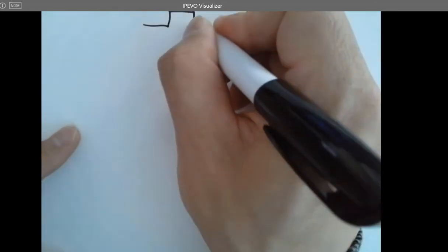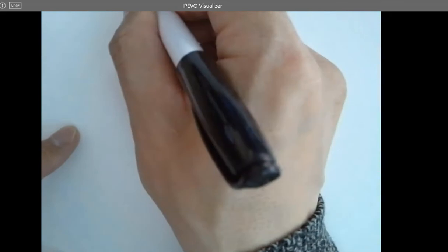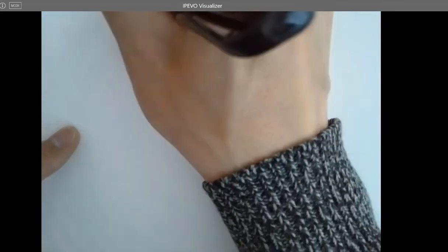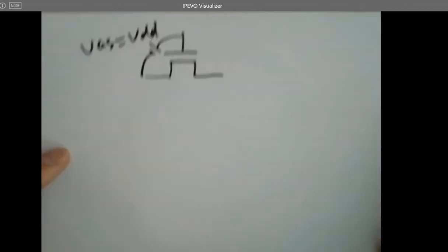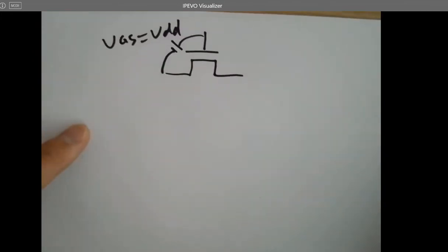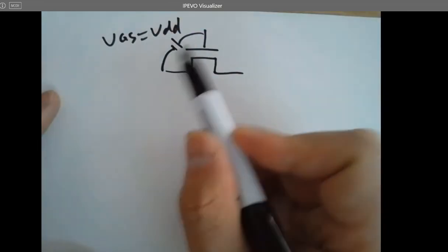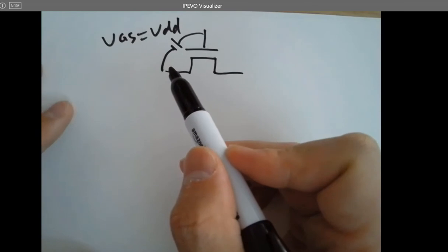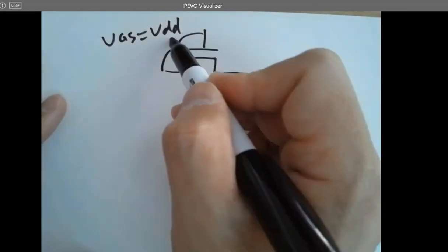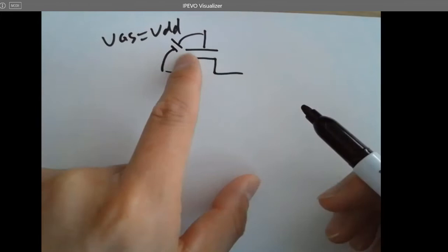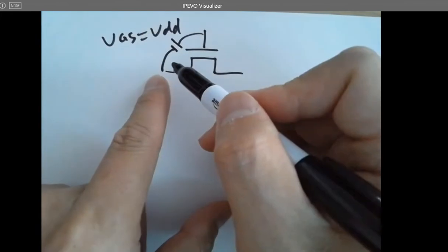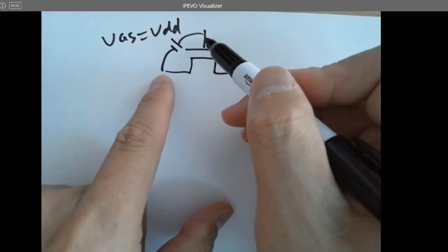So whenever you are using a pass gate to sample, you hope that VGS to be a constant, ideally VDD. I mean for VGS, not VG. VG can be higher, but you do want to keep VGS to be a constant. I mean if you tie a voltage source in between G and S, are you able to change the voltage between G and S?